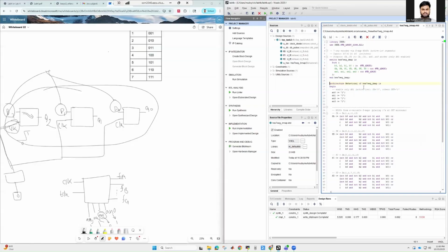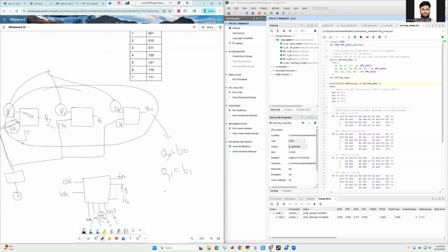Q2, Q1, and Q0 will generate the binary numbers like B0, B1. Q0 will act as B0 to the 7-segment code. Q1 will act as the B1 of the 7-segment code. Q2 will work as the B2 for the 7-segment code. As I mentioned, the 7-segment code we have written for task 1 has 4 bits. There was another bit, B3, but for task 2 we will use only 3 bits. So if you just plug in 0 to B3, then it will work. We are setting B3 as 0, and we're dealing with the 3-bit binary number.